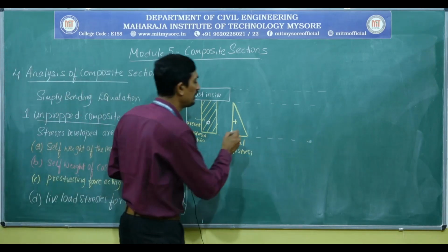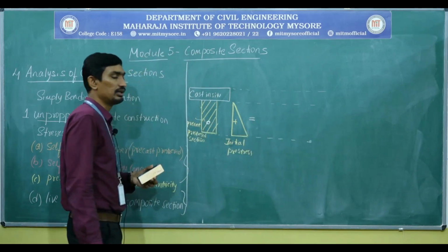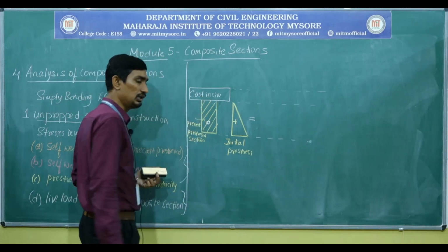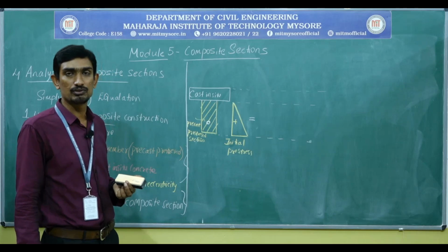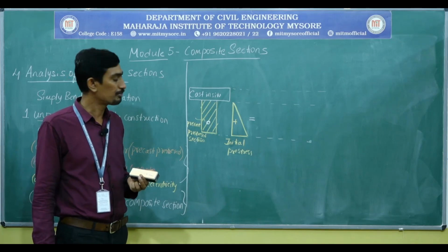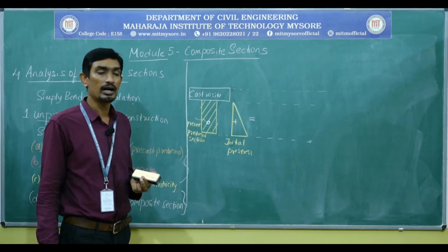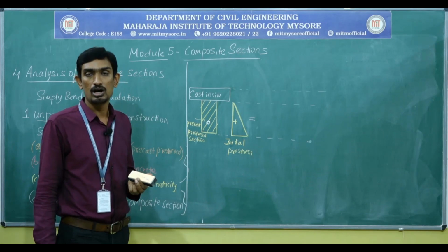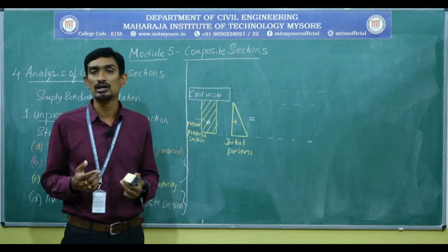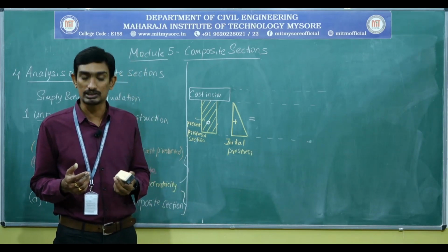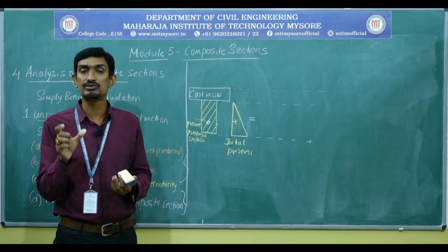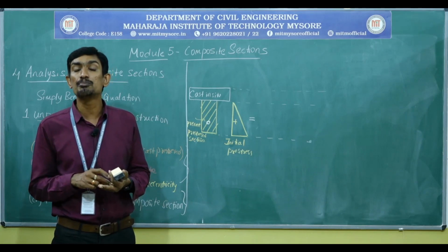So now the very interesting thing that is going to happen is, whatever the pre-stressing force that will be induced in the precast pre-stressed section will encounter certain amount of losses. Neglecting those losses, the left out or net force will be called effective pre-stress.